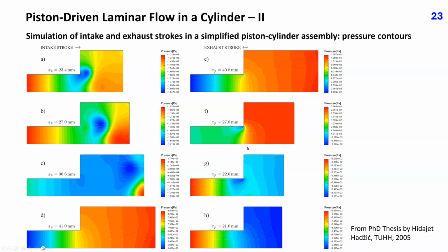This low pressure zone grows with time until, at the bottom dead center, the cylinder stops moving and the inertia of fluid causes a low pressure inside the whole cylinder.